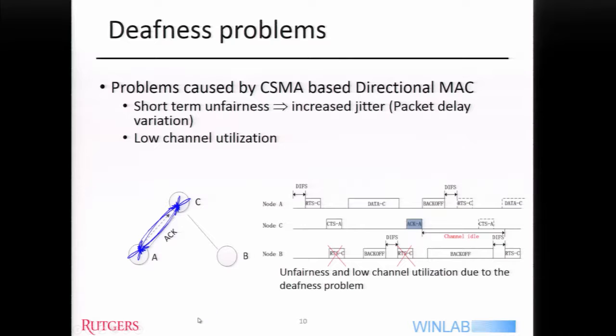But he has to design the RTS to accommodate that. So the next effect is either 20 dB louder, or it takes 100 times longer, because the RTS packet can be transmitted very slowly. It's not trivial, because 20 dB is 100 times the watts, which is out of the question. So then it has to be 100 times longer, which has latency implications.